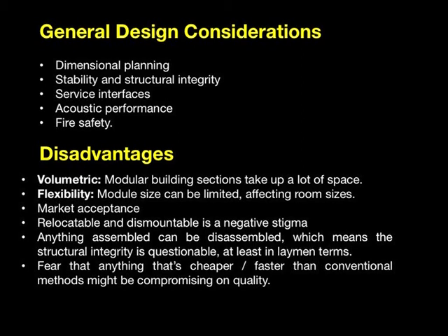For example, the building components need to be aligned in one particular axis. So, even though in regular construction you do not look at the whole building until a very later stage, in modular construction you need to consider the entirety of the building during the conceptual stage itself, because you need to take care of every single component, and only then the modules can be manufactured according to that.